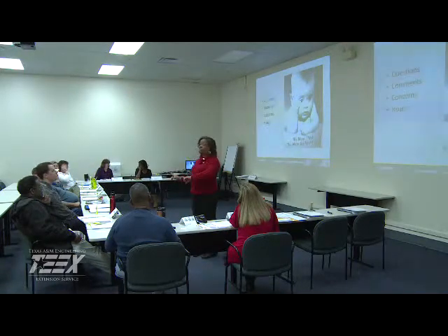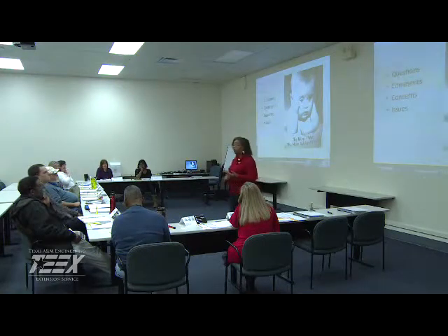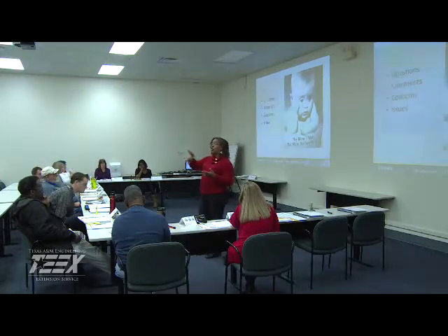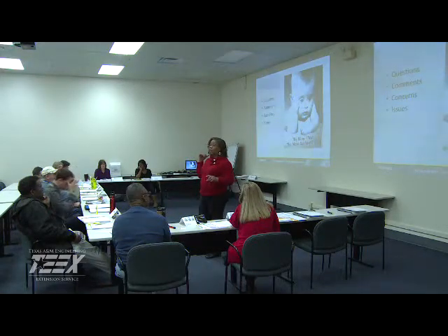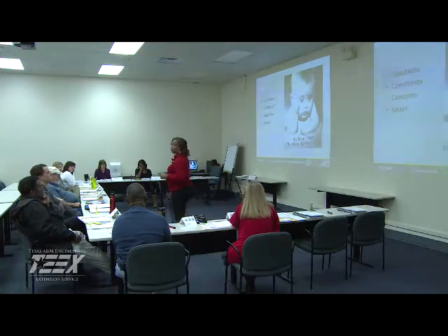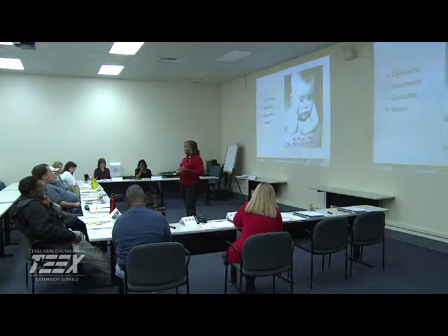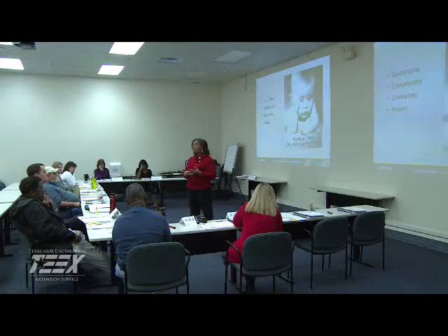Again, it goes back to the system. They're the ones responsible for making sure all the samples are pulled and so forth. You stop it after you have demonstrated that we're within parameters, because what triggers that is the exceedance. When you're over the 90th percentile, that's when you have to start doing that extra higher frequency and doing the water quality parameters, especially if you're utilizing the orthophosphate and the silica-based products there. So after 2 good rounds, they can stop the water quality parameters.